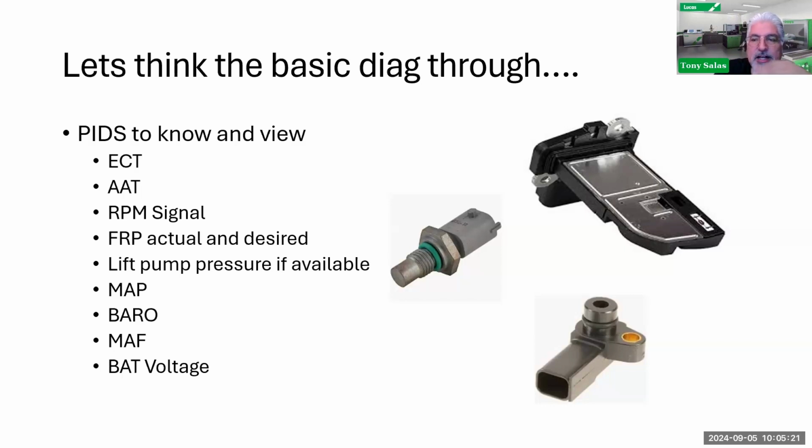Should it be skipping in and out? No, it should not be at all. And by the way, if you've been keeping up on the latest in in-depth diagnostics, since I've been working more with gasoline again, we're now seeing timing wheels or reluctor wheels on camshafts and crankshafts starting to shift. So we're seeing that problem, which will throw a timing code definitely or a no start, and it'll just feel like the timing's advanced, right? So in this case, definitely a problem that we're going to come across.